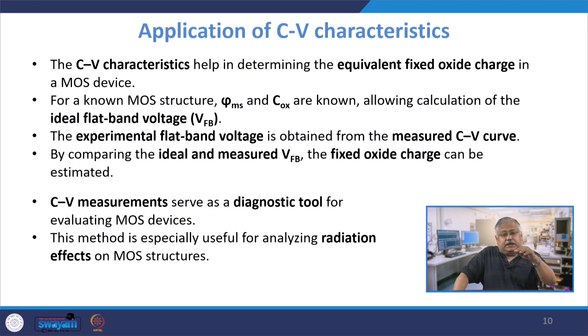But if you change it, say for example, you change the oxide capacitance charges or interface, the shift will be there in the CV. From there you need to find the value of your fixed charges, right. Now, in reality, the oxide or interface trap charges, once they have been formed, typically do not change with a large amount of experiments or external elements. They do not change, they only change in one condition, typically when you are analyzing radiation effects in MOS devices.